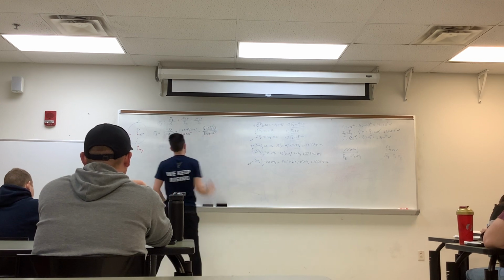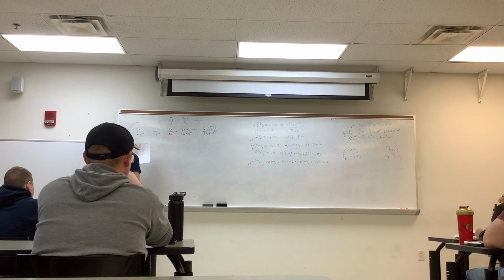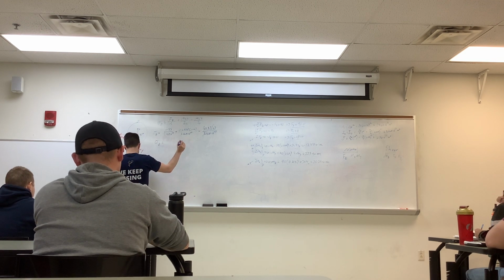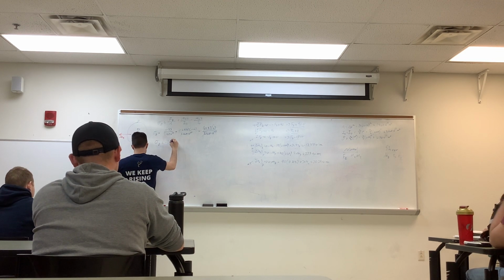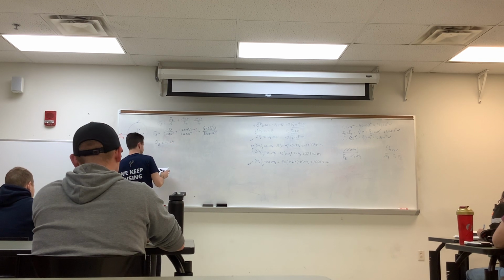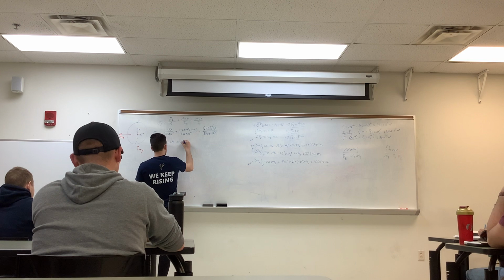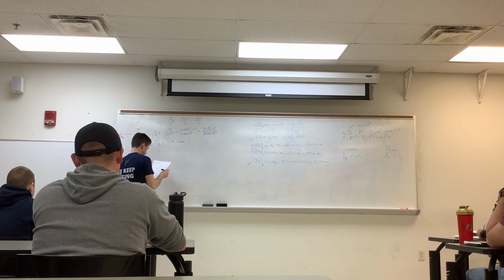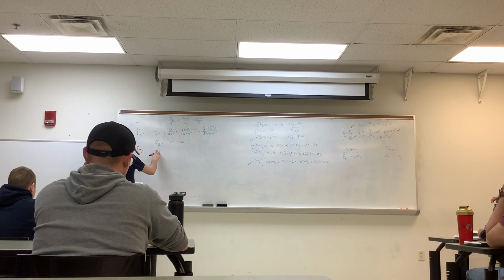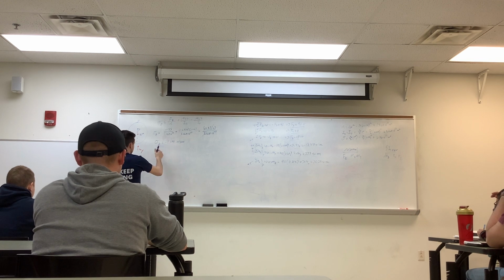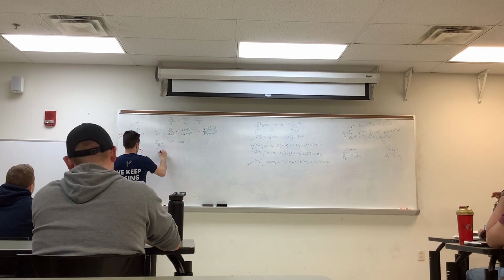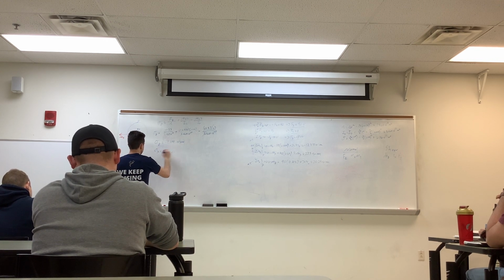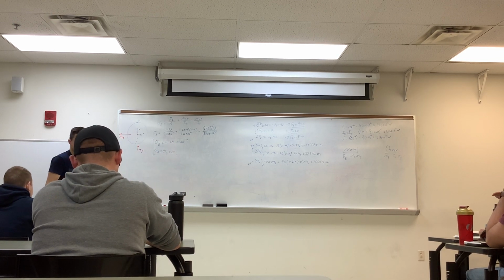This one just turns out to be 0. Doing the algebra for everything, we get this stress in the z is negative 1.04 MPa. In addition, the two that are based on our coordinate system, sigma x is equal to sigma y is equal to 0. So we have all of these so far.